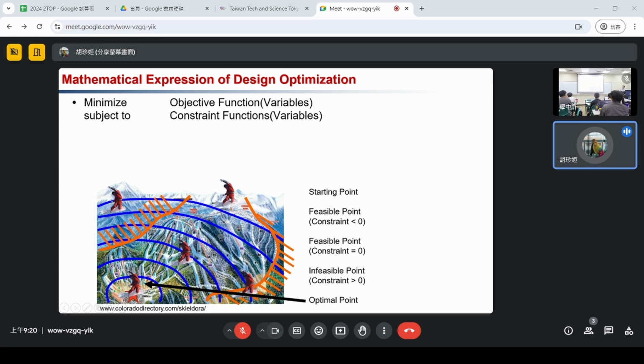Now, if I can change the thickness of the soft robot wall, is there any limitation? If it's too thin, it cannot be manufactured, or it can break easily. If it's too thick, probably it doesn't bend, it doesn't deform. So there's always a range.